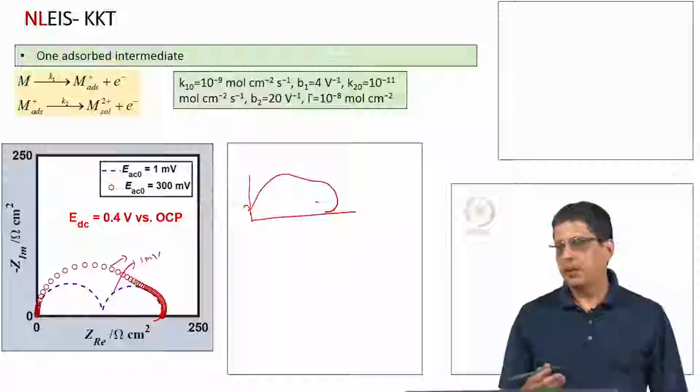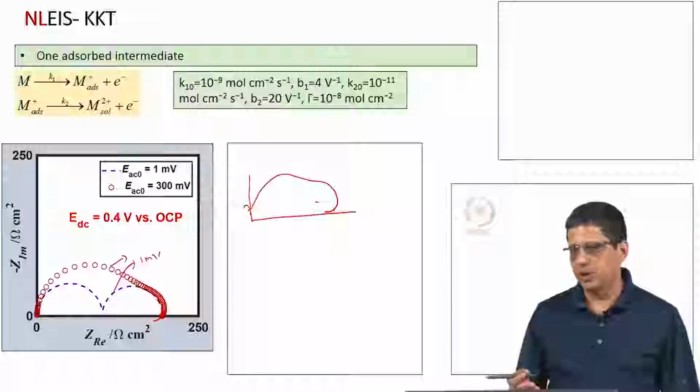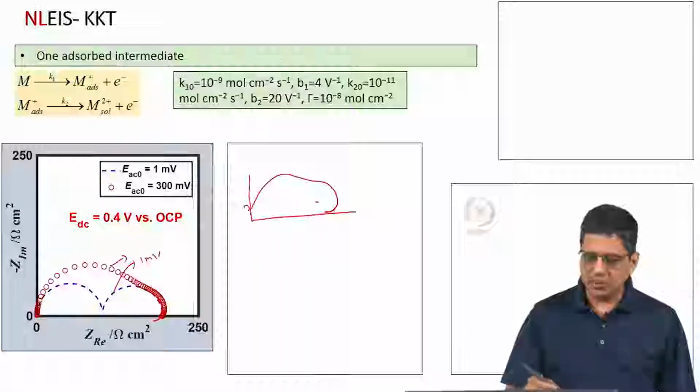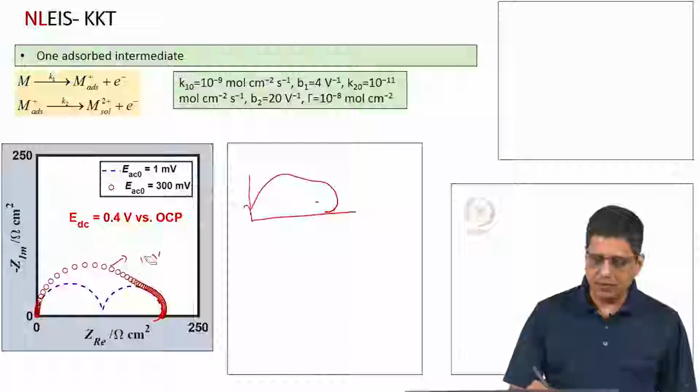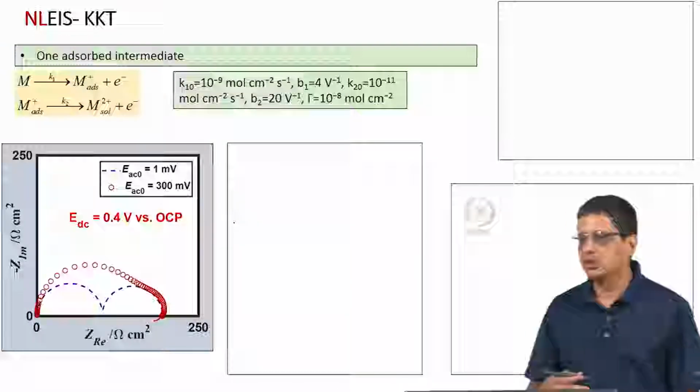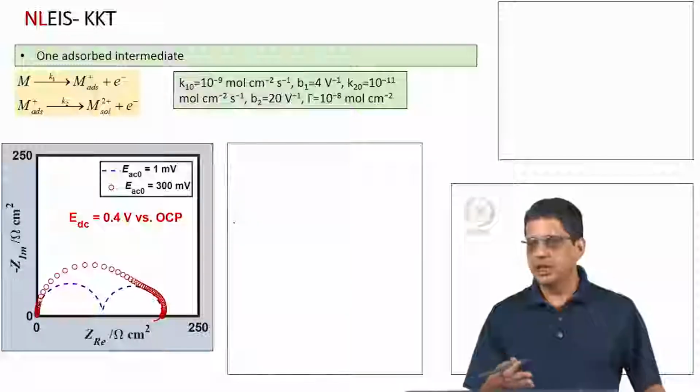Normally one would not apply 300 millivolts of perturbation amplitude, but here we want to exaggerate and see the features very clearly, see the difference between transformed and original data very clearly. Therefore, we have used a very large perturbation amplitude. The code that is used to generate 1 millivolt can be used to generate 10 millivolts, 100 millivolts, any such amplitude.